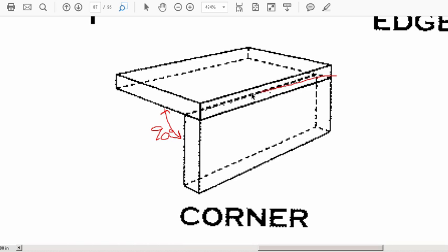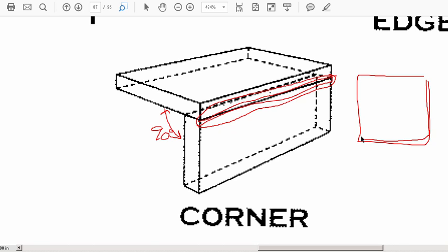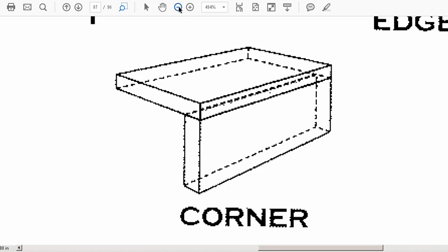The actual weld will typically occur on the outside of the joining members, and this is the kind of thing you see in tank or box welding, where you don't do a lot of structural welding on the inside of the feature, you do on the outside. So this is your plane of work, and obviously a zone of stress that occurs in the parts too, especially if you think of like a tank situation like this. This is where you're going to get a lot of stress and where your corner joint's going to come into play. Alright, so that gives us the overall concept of the type of situations where we're going to weld.